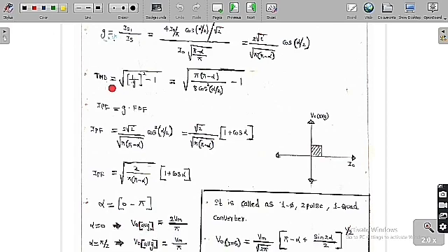So THD, the total harmonic distortion, is equal to under root of ((1 by G) whole squared minus 1). You know the value of G, substitute here, and if you do the simplification, finally we get under root of (pi into (pi minus alpha) by 8 cos square alpha by 2 minus 1). This is the value of the THD, whereas the THD in the full wave bridge rectifier is 48.43%, independent of the value of alpha, whereas in the semi-converter it depends upon the value of alpha.